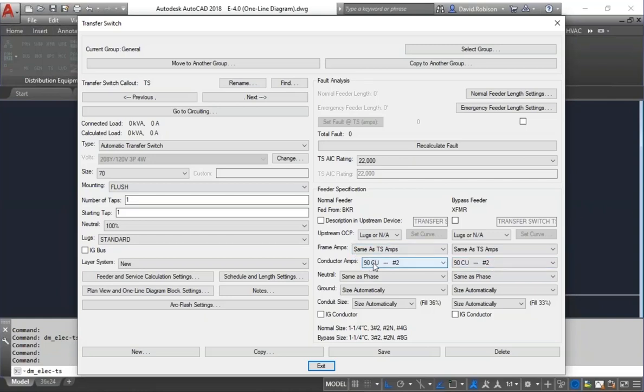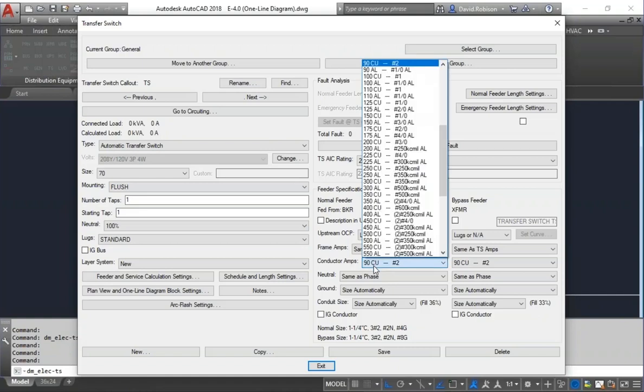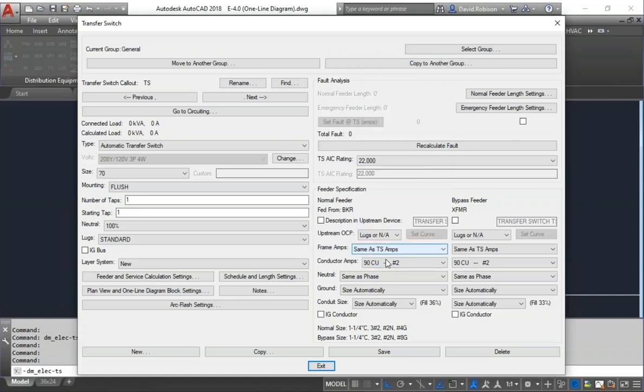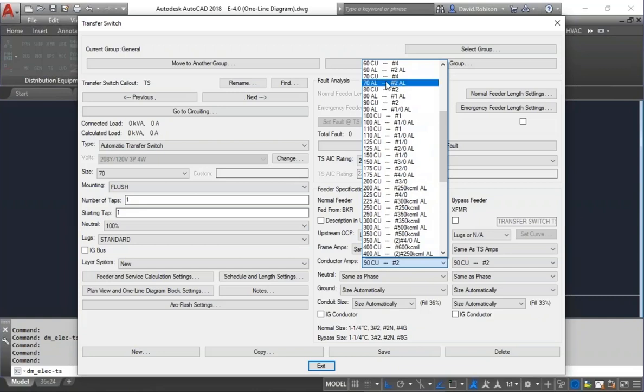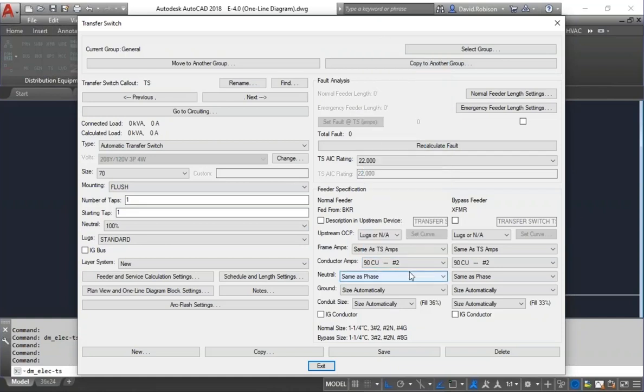For equipment grounds, when you upsize your conductor, you have to upsize the ground with a proportional area as you upsize the conductor. So he went from a 70 amp conductor, which is a number 4, to a 90 amp, which is a number 2. So since the wire size got bigger, the ground size also has to get bigger. So that's why you went from a number 8 to a number 4, is how that ends up working out for that calculation for those 2 sizes.